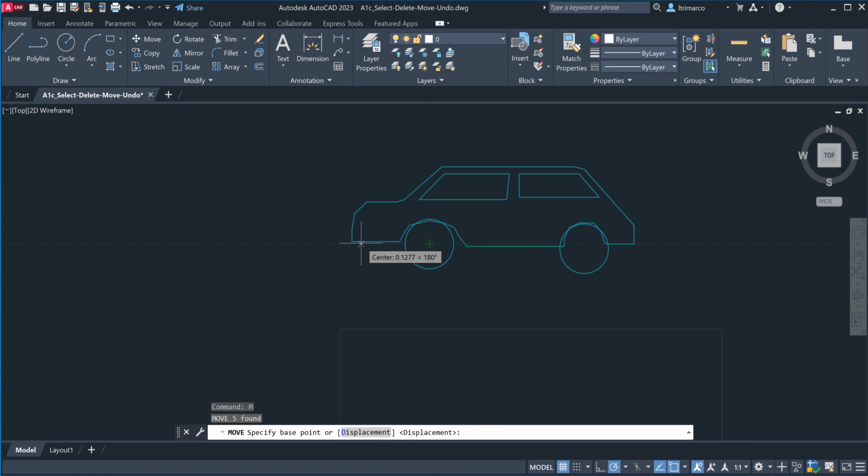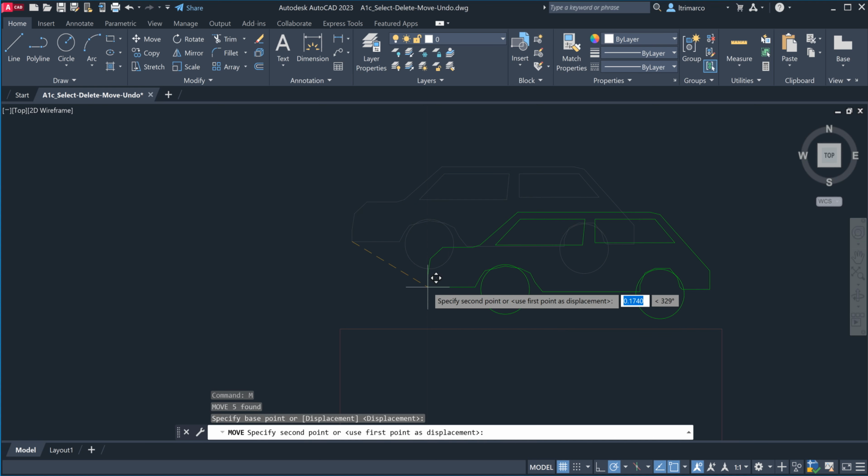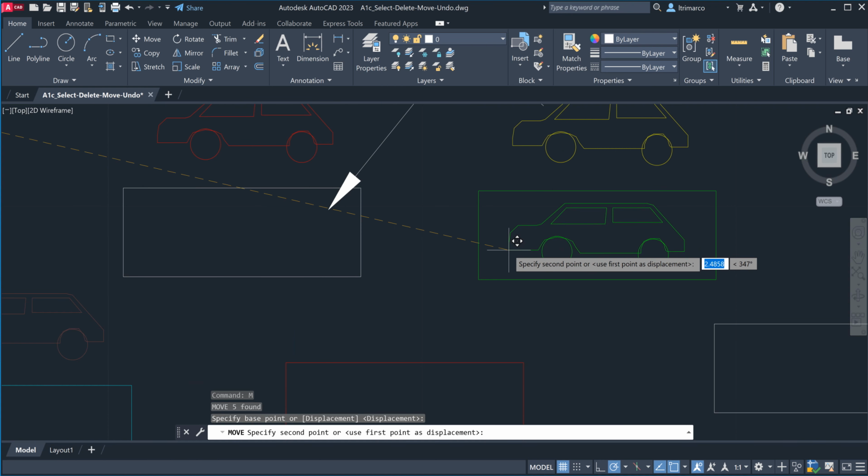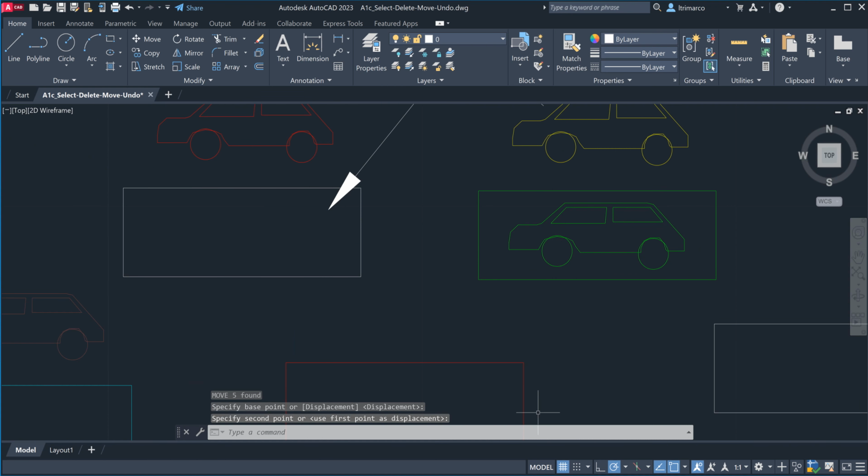If I want the midpoint on this line, I move my cursor near it, and a flag will pop up with the symbol to tell me. So I have to help AutoCAD along with my object snaps. But once I've selected an endpoint or a center point, I know I'm moving it perfectly from the object's specific point to somewhere within that interior box.